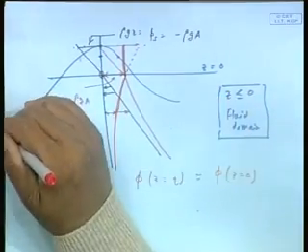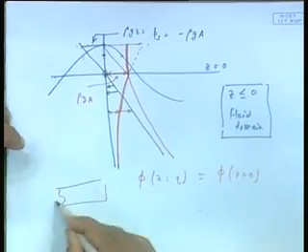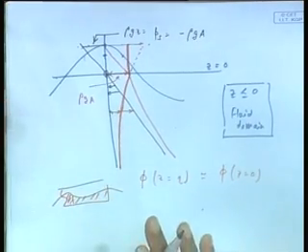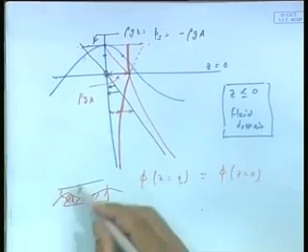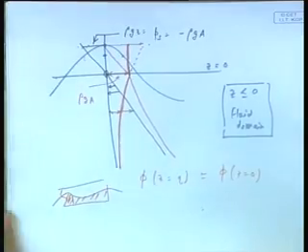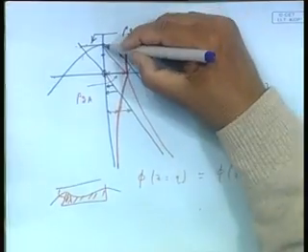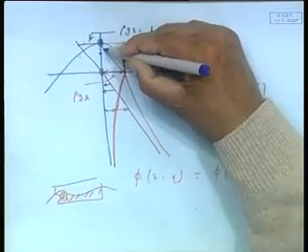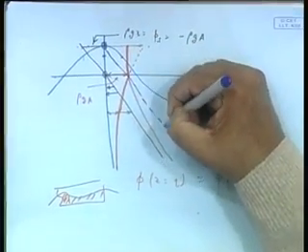Supposing I want to use hydrostatic pressure, as you have done sometime in ship strength. In ship strength, if you recall, you simply take a ship, you have this profile, and you find this buoyancy curve based on this buoyancy. That means you are using only hydrostatic pressure. What you can see here is that, supposing I use this as my datum line, this was my z equal to 0, what would have been my hydrostatic pressure? It would have been like that.